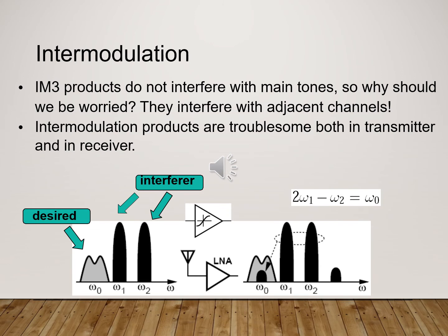Now, intermodulation or IM3 products do not interfere with the main tones, as you see in the previous slide. So why should we be worried about them? We worry about them because when we use multiple channels on a frequency band, they will interfere with adjacent channels.